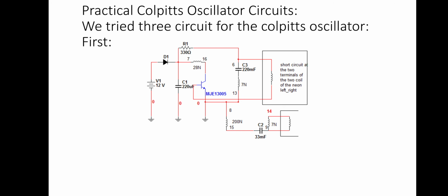The capacitors CC and CB, the base capacitors, coupling capacitors, are employed to block DC, and they provide an AC path. The radio frequency choke offers very high impedance to high frequency currents. That means it shorts for DC and opens for AC. Hence it provides DC load for the collector and keeps AC current out of the DC supply source.